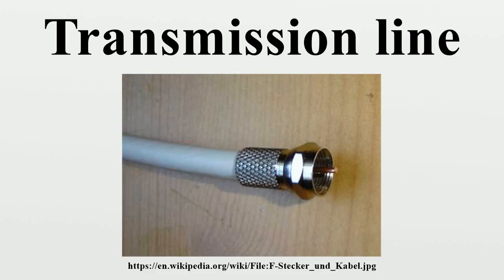Single-wire line. Unbalanced lines were formerly much used for telegraph transmission, but this form of communication has now fallen into disuse. Cables are similar to twisted pair in that many cores are bundled into the same cable, but only one conductor is provided per circuit and there is no twisting. All the circuits on the same route use a common path for the return current. There is a power transmission version of single-wire earth return in use in many locations.